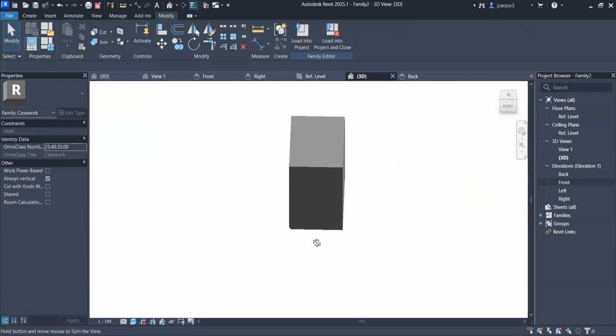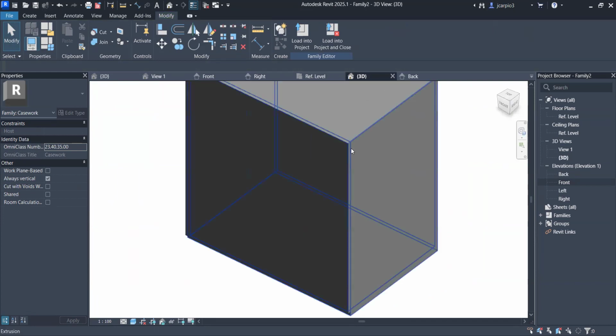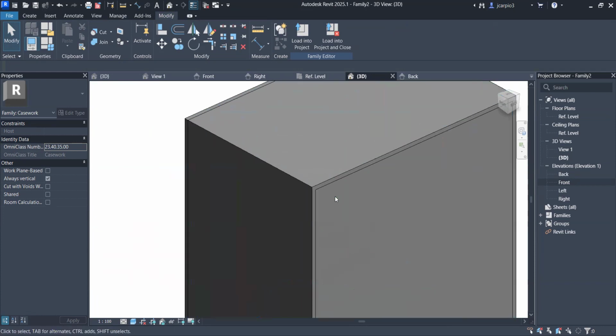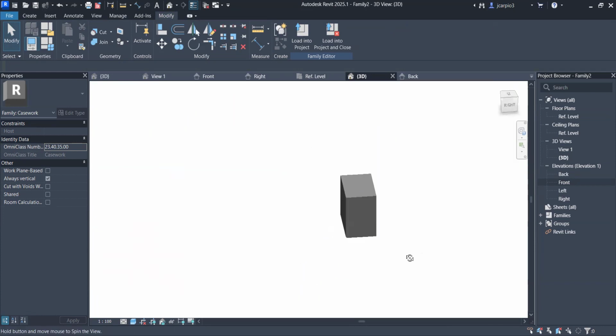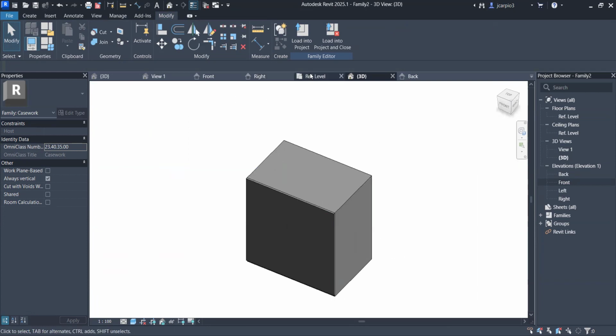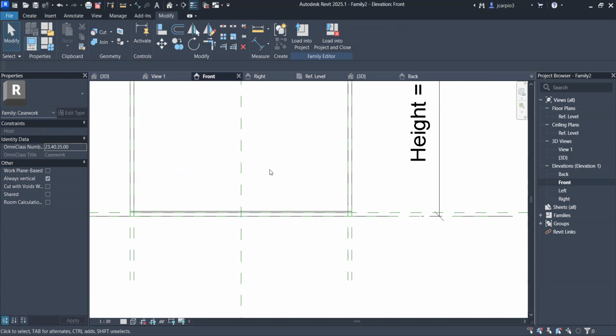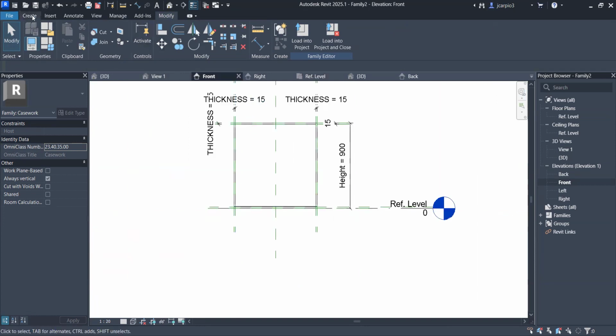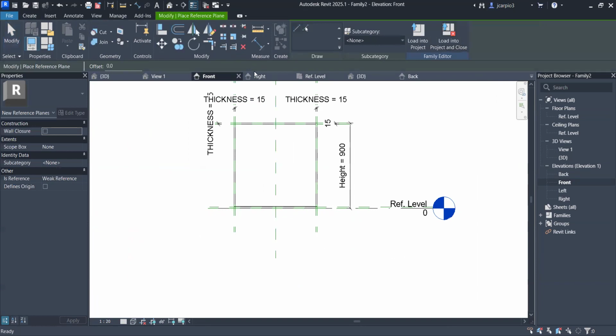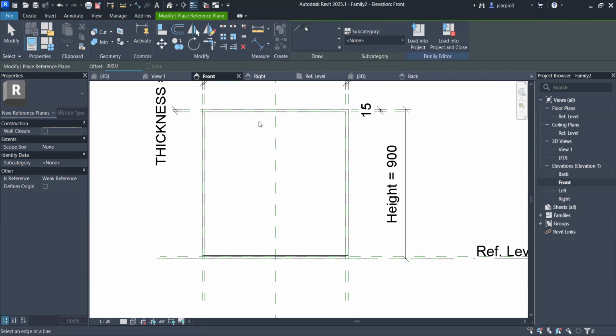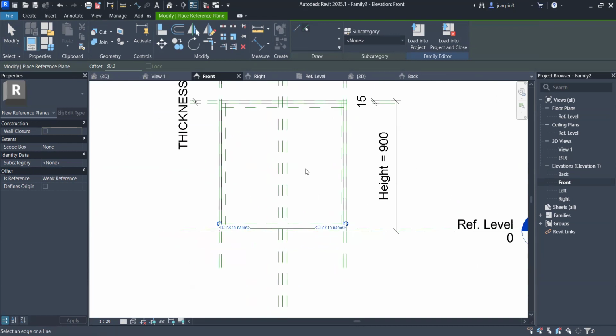you now have the front and back side of the cabinet. So for the door frame, you just need to go back to the front elevation, have all the references and create the reference plane, have it on the thick line and assume 300 mm for the offsetting and 30 mm. You start offsetting all the side corners and elevations.